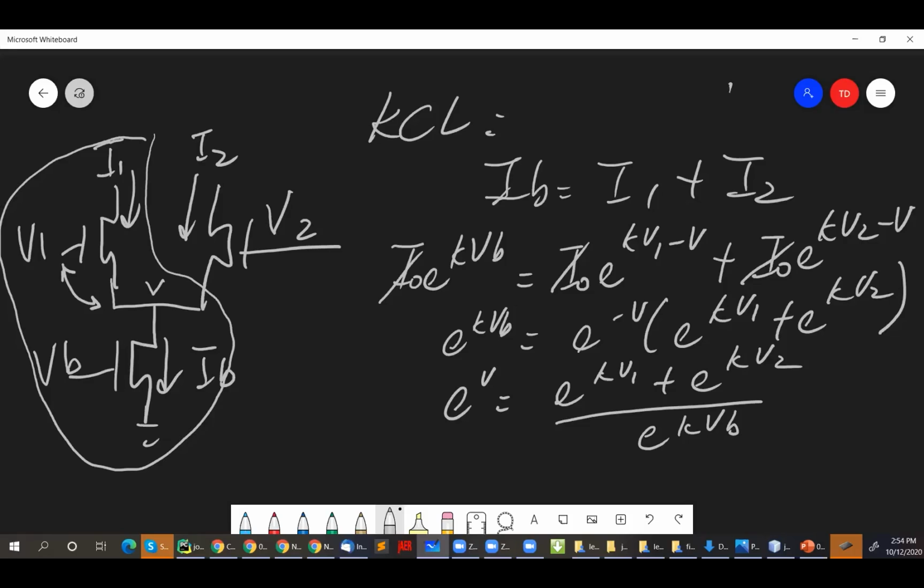I don't need to know that kappa is 0.7. I just want to know what that circuit's doing. And so it's just easy sometimes to drop the kappa just to reason through the circuit. And once you can reason through the circuit, then you better put all your kappas back because you're not going to get the right current. It's a function of voltage. Okay. Yeah, it's just easier for intuition.